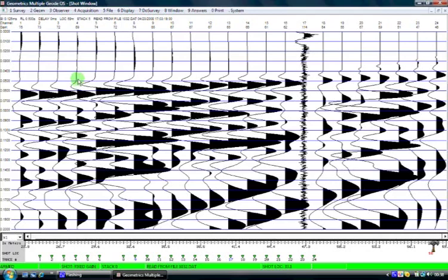At the moment, if I wish to increase the amplitude of these and therefore process the data with a greater accuracy, I can stack more times with the sledgehammer, which will increase my signal to noise ratio and make these first arrivals sharper.